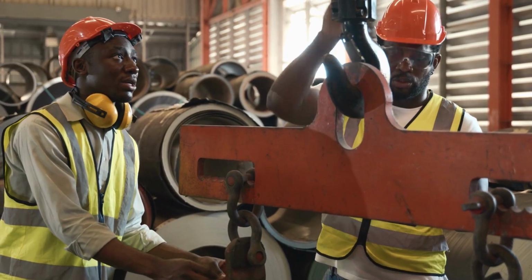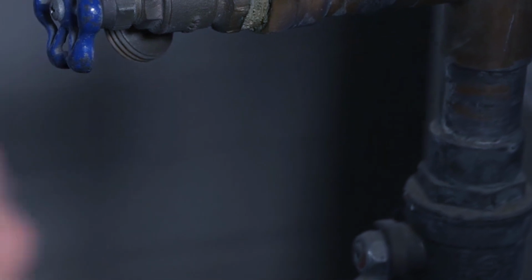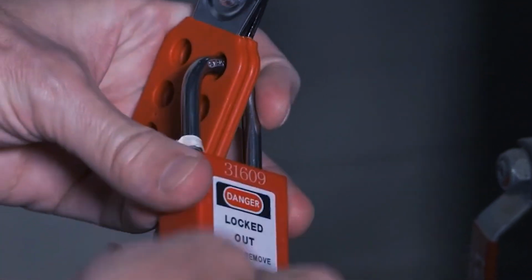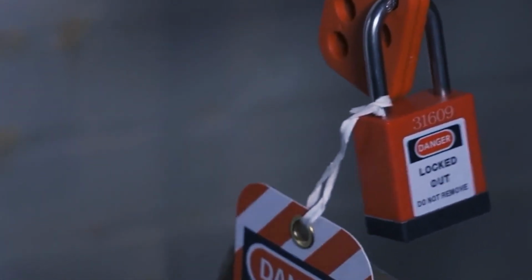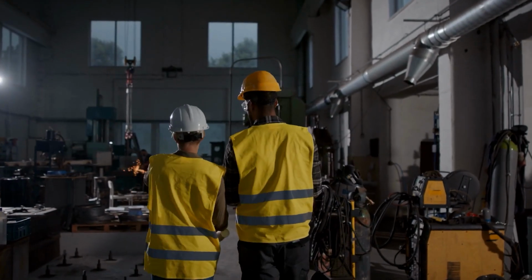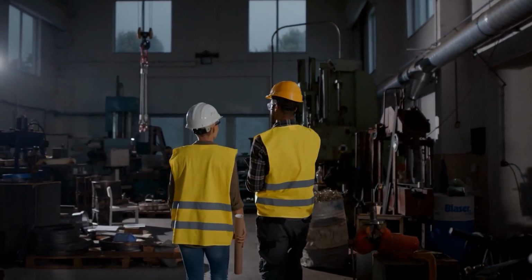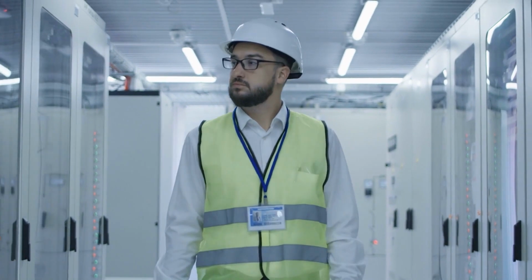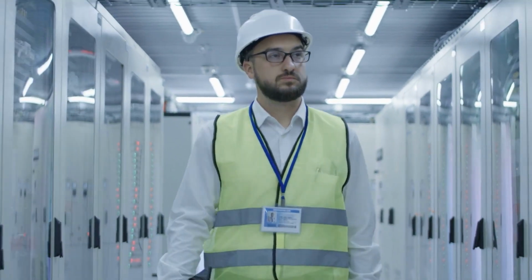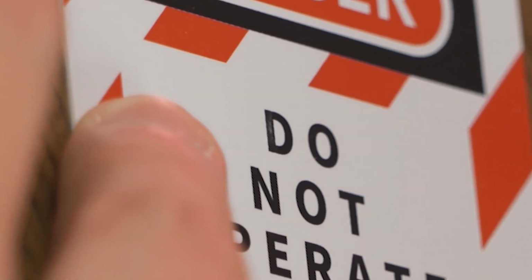Nothing besides protocol. To add another layer of protection, tags are equipped with the ability to be locked. A tagout device is one that uses a positive means such as a lock, either key or combination type, to hold an energy-isolating device in the safe position and prevent the energizing of a machine or equipment. Sometimes it is not possible to lock out the energy-isolating device associated with the machinery. In that case, you must securely fasten a tagout device as close as safely possible to the energy-isolating device in a position where it will be immediately obvious to anyone attempting to operate the device.